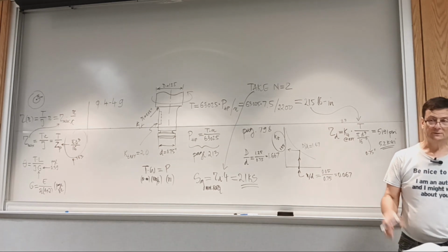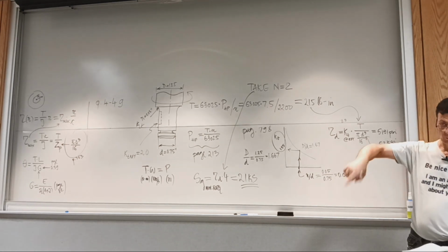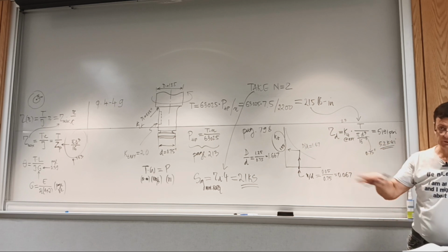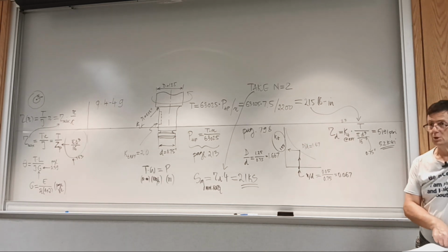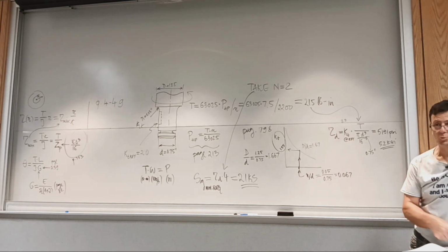21 ksi yield strength minimum required for the material to use it for this mower shaft, which is actually the crankshaft. The mower, the one that drives, there's no gear reducer in between, or any kind of reducer. So we go back to carbon and alloy steels, and remember the slogan: use the worst good material for the job, worst being cheap.